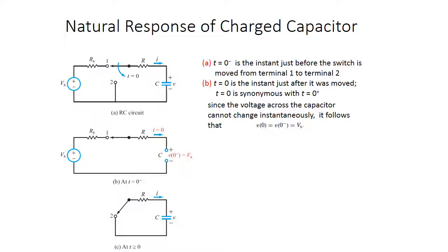This circuit B is showing that we have a power source Vs, and that's going to go through two different resistors through the switch, and nothing's going to happen. It's going to be an open circuit at the capacitor because this capacitor is fully charged. The current going through it is 0 at that point. That means that entire top line is a supernode with the same voltage as your source. Because remember, there's no current flowing through it, so it all has the same voltage.